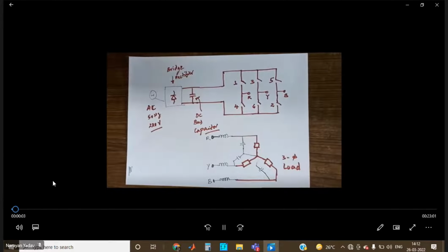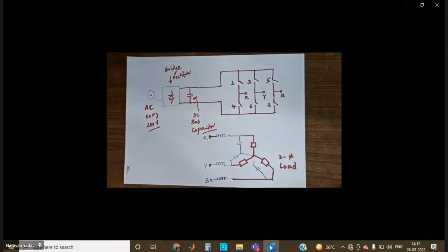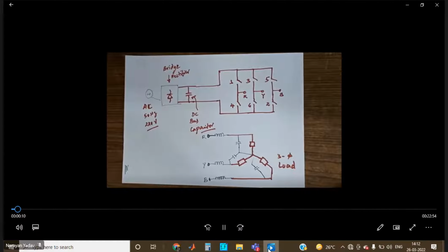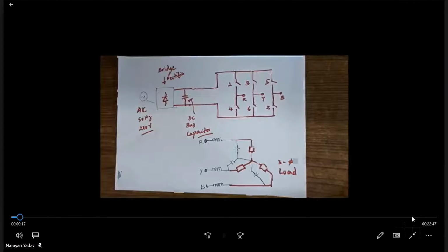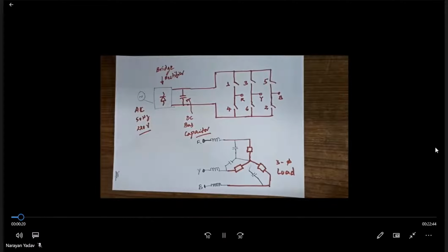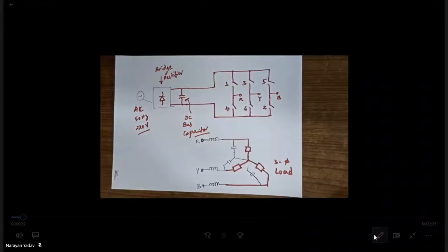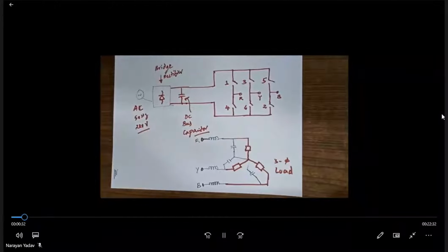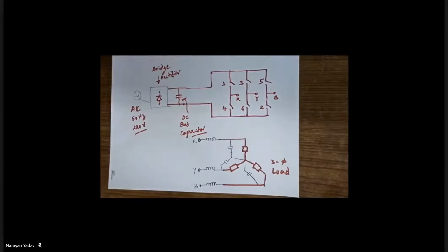In this experiment, we will be demonstrating the three-phase inverter and its functionality. The three-phase inverter essentially takes a single DC supply on the input side, whereas on the output side you will get a three-phase AC supply. In this case, output voltage as well as frequency are both controllable. Whereas in a conventional three-phase supply, we can control the voltage magnitude, but there is no control on the frequency. The frequency is 50 Hz in the normal operating condition, and voltage is 440 volts three-phase AC supply.